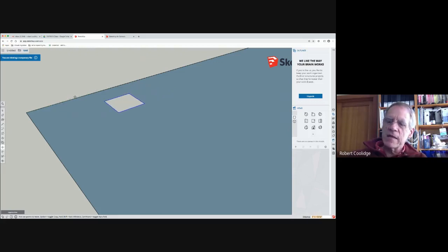If I wanted to make a copy, you hit the Option key on the Mac. I think it's Control on the PC. So now the original is still there, and I'm moving a copy. For replicate, I can move it one spacing and click, and there's the first copy.